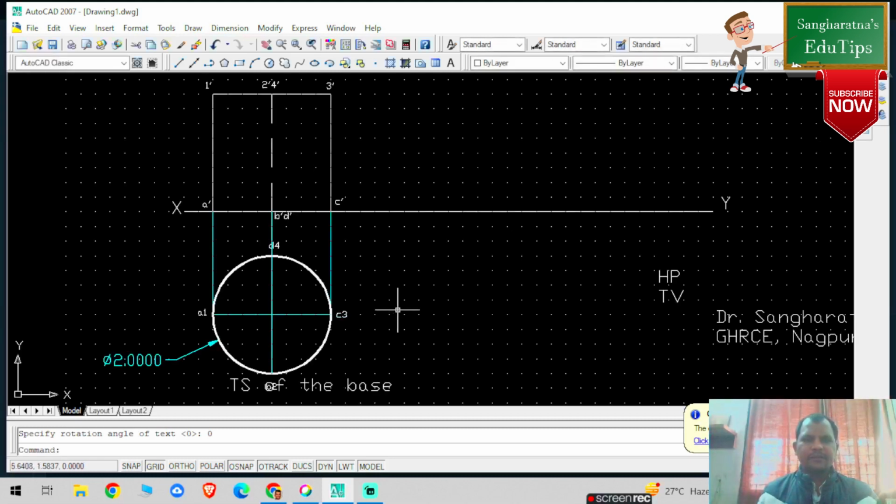Press escape. Okay, now what I'm going to do is mark the midpoint of this axis. So here I'm going to select the point, and this will be I think the midpoint of this particular axis. And from this particular point I'm going to draw one sectional plane, which will be inclined 45 degree to HP.